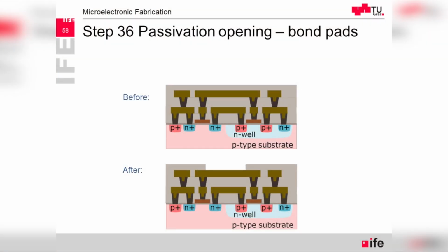Also for the modern technology nodes, starting from 50, 40 nanometers, where we also have metal gate, in order to improve mobility of charge carriers in the channels, we will have some additional liners in the gate.